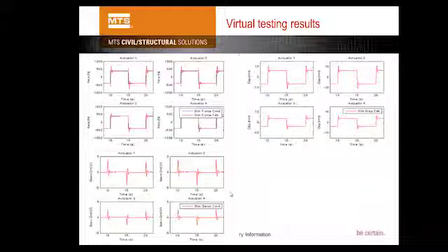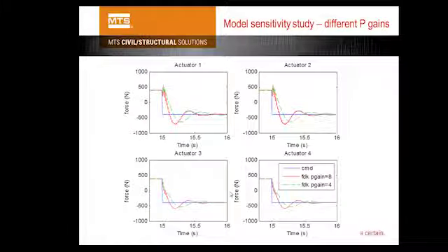So you can do a side-by-side comparison and study like that. This is like a sensitivity study. Basically, I'm trying to see what if I have a different peaking. A lot of times when you tune a system, you first work on the peaking. If the peaking is low, like this green curve, the dynamics is slower, so you need a longer time to reach the steady state. And the overshoot is also smaller because it's less aggressive peaking.